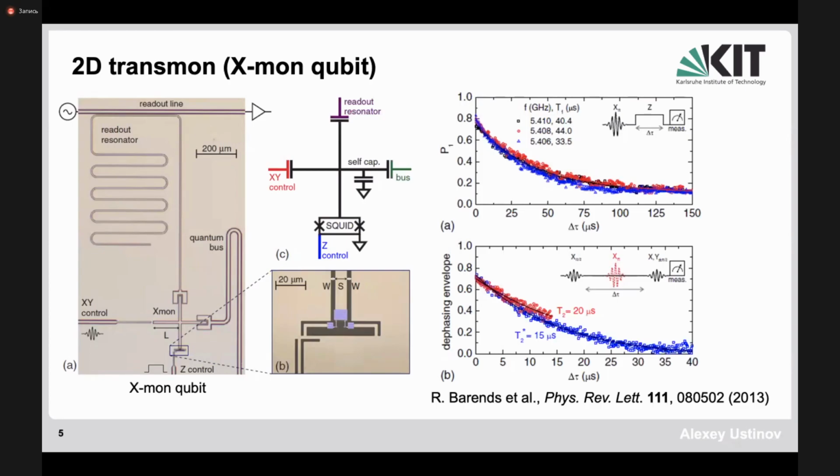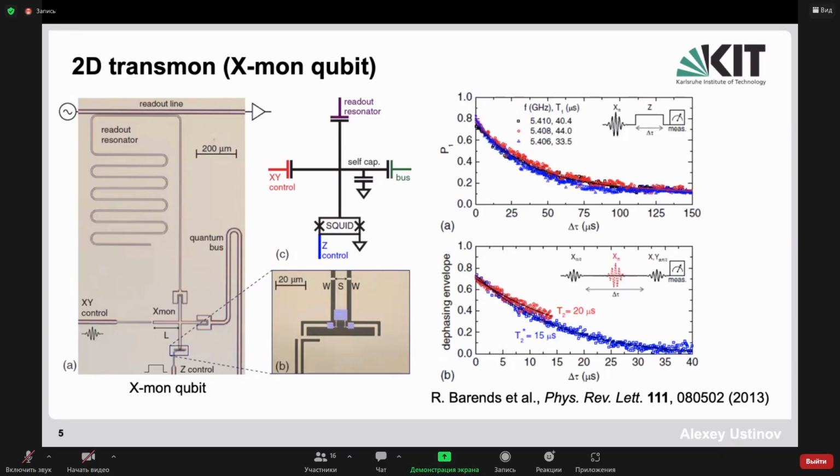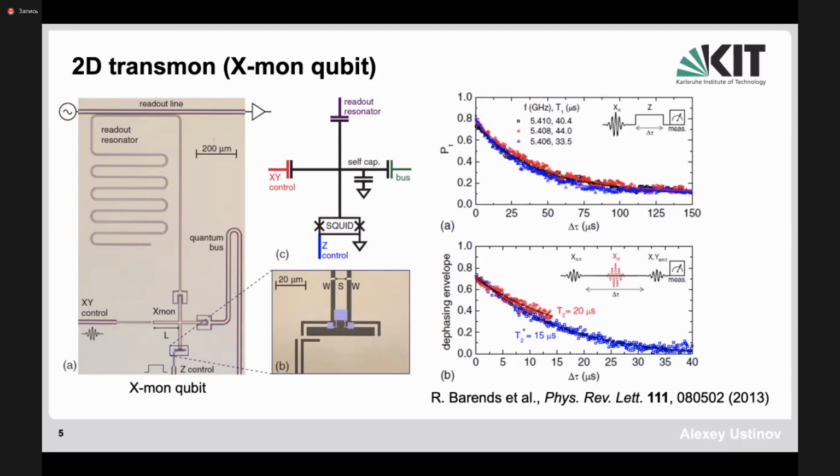And as I told you, also naturally, this frequency depends on the length of the resonator. So it's feasible to use multiple resonators at different frequencies, coupled to the same readout line, to read out multiple qubits. So typically, people use 8 to 10 qubits at maximum. And the reason is the limited saturation power of the preamplifier, which we will discuss a bit later, the so-called parametric amplifiers used in modern quantum architectures.